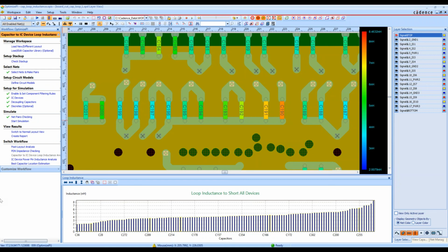It's almost like traffic. If you go down from six lanes to one lane, everything is channeled into that, the density becomes really high, and it becomes problematic. And if you fan out right away after that, it doesn't necessarily help that much. You want to reduce those points where everything is being focused and the density gets high, just to allow current to travel more smoothly.